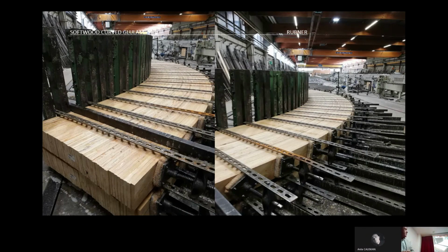I want to go back now to glue-laminated timber, where again, using lamellas, but making them into structural portal beams, which can be as strong, if not stronger than steel, to make unsupported beams without any columns or anything like that. Sometimes up to 50 metres, depending on the size of the beam. These are some quite large curved beams, which I took a picture of a few years ago. Again, these are softwood. I have to go back to softwood occasionally to show the capability and the curves that you can get and how you can engineer timber to make these structural beams.